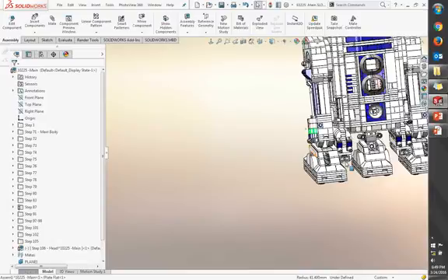I'm not going to use this part in any other assembly. If I do, I'll just recreate it, because it's actually easier to recreate it than it is to try to get this to work here and here and here. On top of the fact, we're using in-context relationships as well too. So it's not going to be easy to put into another assembly, especially if it's wiggling around and whatnot.